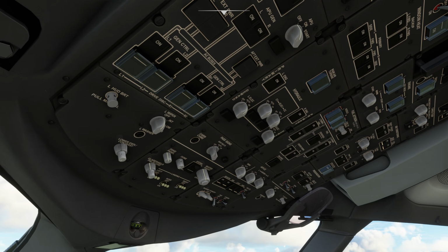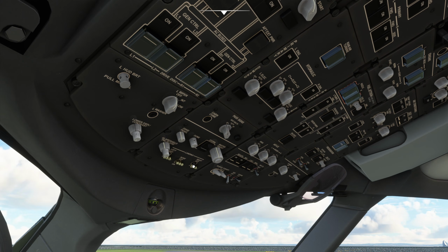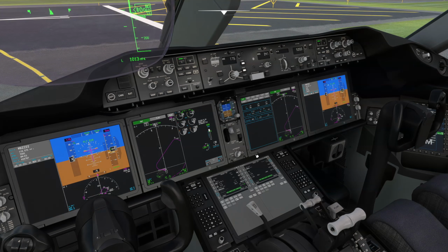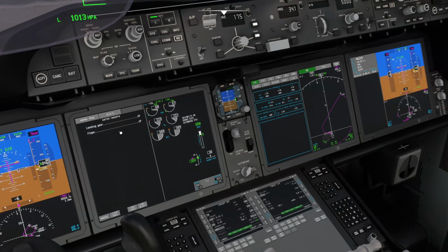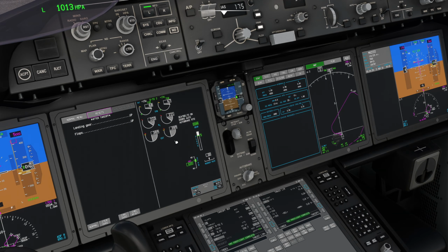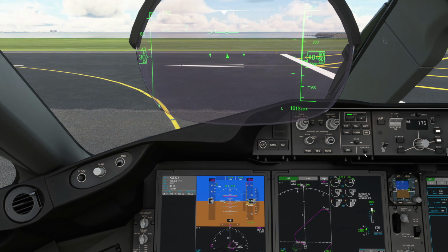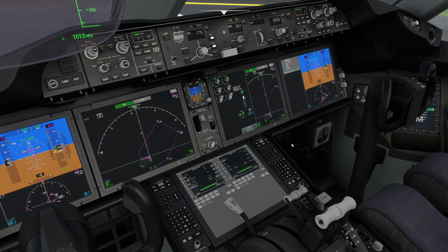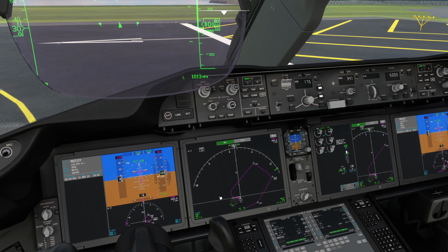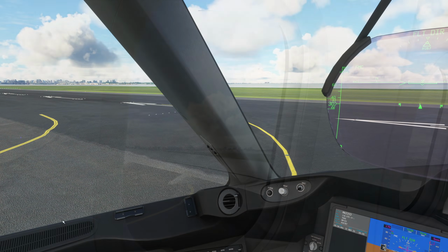As we roll onto the runway, we're going to make sure that we have the left and right landing lights on. We don't use the nose light typically, and put the strobe lights on as well. Depending on the airline, you might alert the cabin crew as well at this point. There could also be a normal checklist to do, so let's see. No, it's already loaded up with the before takeoff checklist done, so I'm going to put that back to ND. Now, it's quite common for the ICAS, this engine display, to be over on the other side for the pilot monitoring to have, and the PF will keep the big screen, but we're going to keep it here for simplicity of making these videos today.